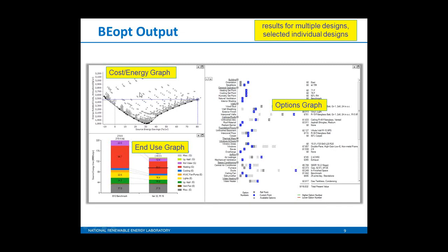And then all the results for these different simulations are saved, and you can select them. And based on what point you have selected, so here we've got a point selected at 80% energy savings, you get a breakout of the energy use in that design relative to your sort of baseline or reference design. So you can see the reduction in energy consumption based on efficiency, the smaller bars here. And also this line here represents the PV production. So not only do we have reduced consumption in our building in this 80% efficient building, but a lot of it is being offset with PV as well.